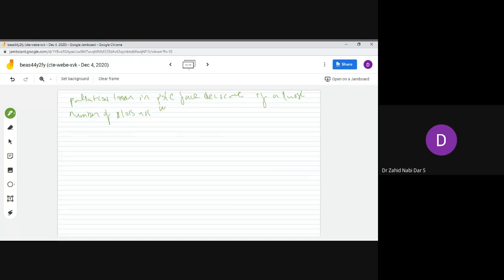So there is a balance between the maximum number of slots we can use and the lesser number of slots. In some cases we will look at a larger number of slots because we have to counter the pulsation. A large machine has greater pulsation losses, while a small machine has lesser pulsation losses and can tolerate them, so we will save in copper. This is how a design is incorporated.